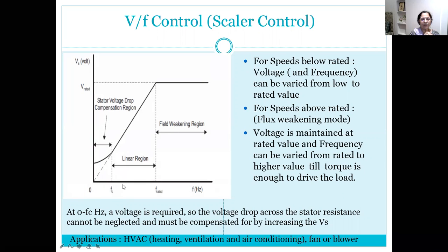If we keep on increasing frequency up to rated frequency value and we keep on increasing the voltage proportionately up to rated voltage, then we can operate this in a linear fashion, where in the linear region the voltage to frequency ratio will be maintained constant, because this is a straight line relation. The dotted line indicates that the straight line can emerge from 0 up to rated condition.